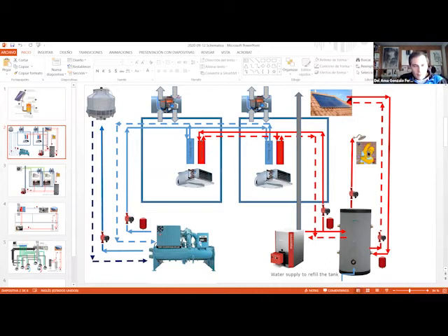What is this? This is a chiller. Is this the air-cooled chiller or a water-cooled chiller? It looks like a water-cooled chiller. If this is a water-cooled chiller, it has to be connected to the cooling tower on the top of the building. Okay, and to move the water, we need a water pump here. Okay, that's perfect. And then the other circuit, it connects the chiller to this.